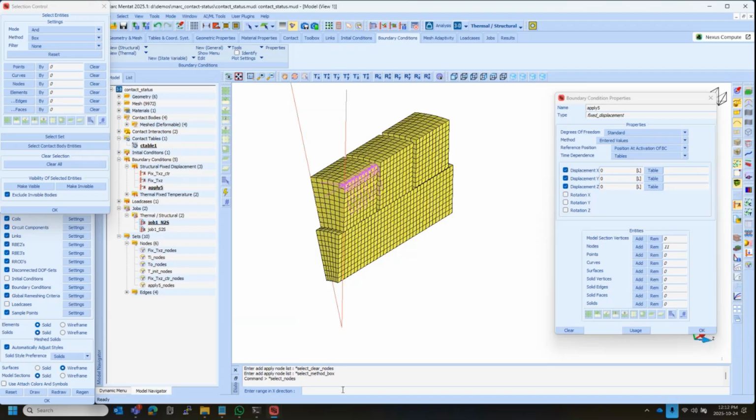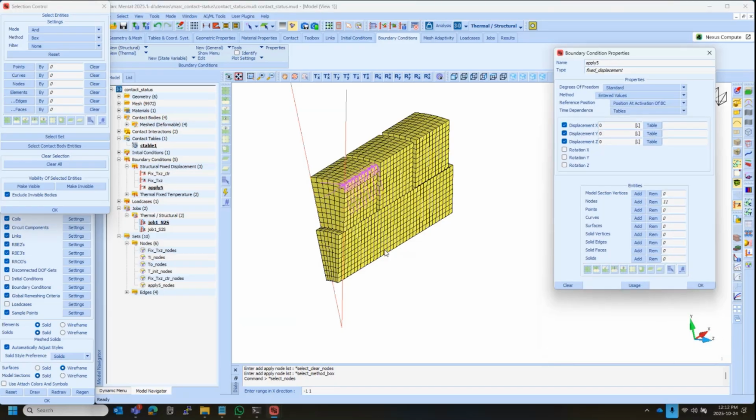So let's say in the X direction from -1 to 1, it should be somewhere over there. Then in the Y direction, let's just show the coordinate system. Y direction, I want it from 1 up to, let's say 3 to ensure that it's fully enclosed. And the Z direction, I want everything, -1 up to 1. Okay.